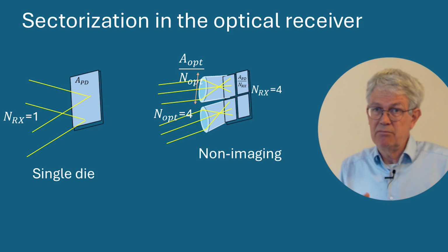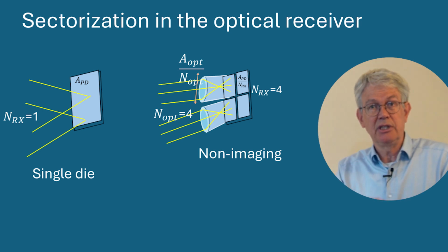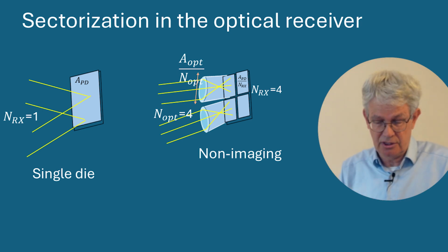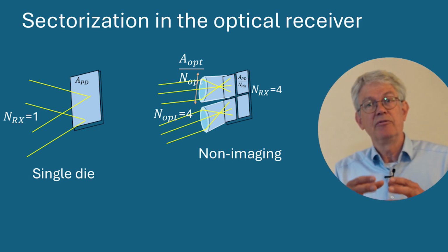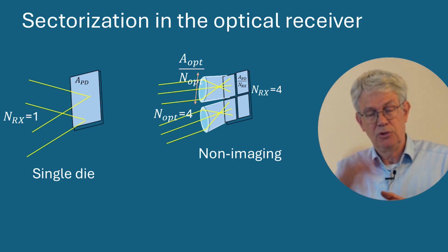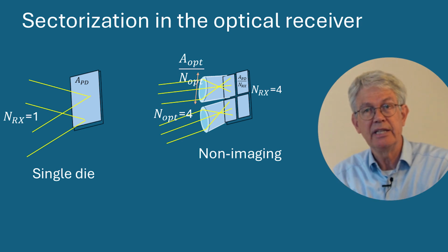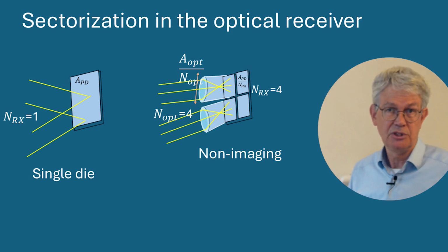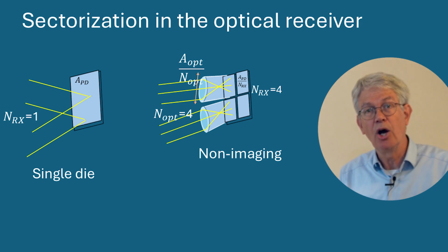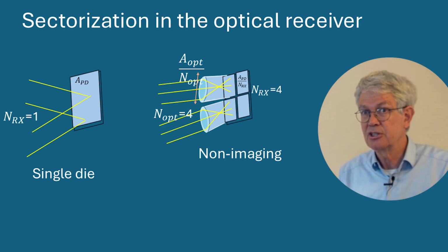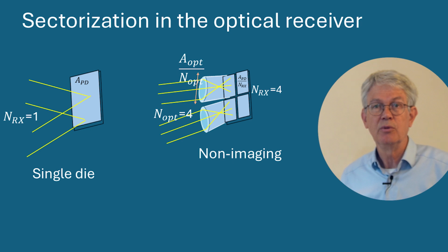And if I just say that what is limiting the size on the device is the hole in the box, the total area, so if I have a limit to the optical area on which my photons fall in and I split that by having n sectors, then I have to divide the effective area by n. And that means that the signal-to-noise ratio goes down with n squared.